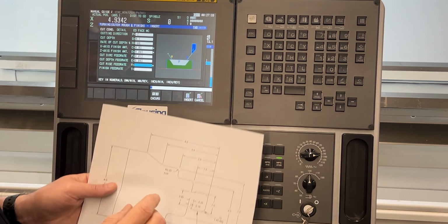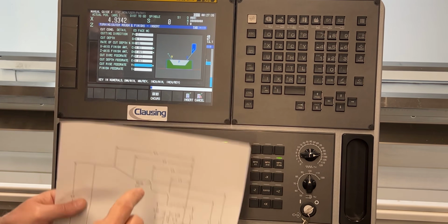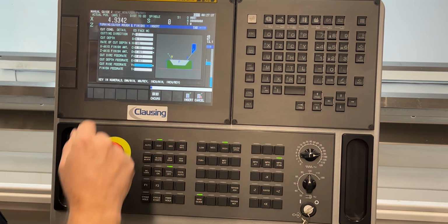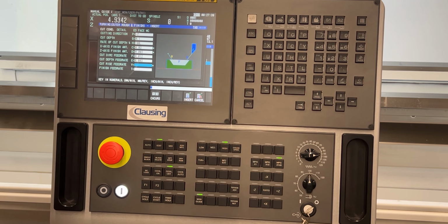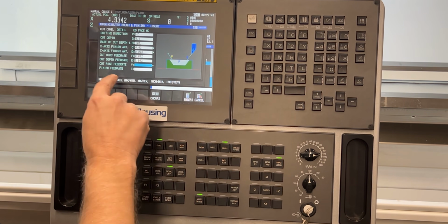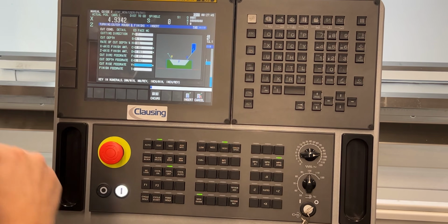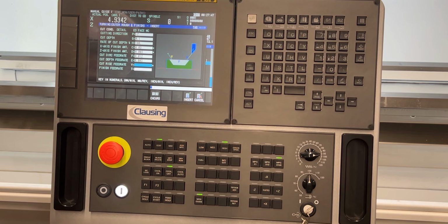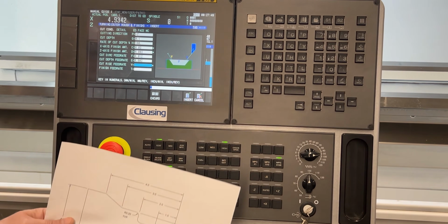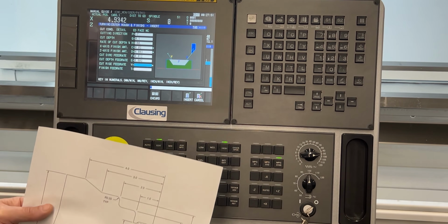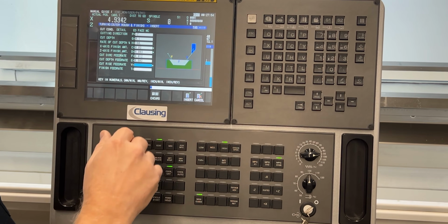I don't have a re-entrant shape that I'm going to deal with on this, but they don't have the asterisk there, so I have to put a value in there. The cut rise feed rate is if it was coming back out of a re-entrant shape. The other place I've seen this take effect is when it's coming out of a radius. It will also use this feed rate.